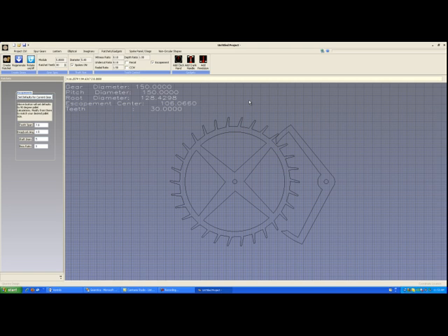The second part of the escapement is the pawl, this longish looking thing here with the 2 levers. This is actually not a longitudinal type device. It is considered as a round wheel, which interferes with this round wheel. They're actually meshing. They just look as if they're too close to mesh. The distance between the pawl and the deadbeat gear centers, this distance here, is extremely important. Even a deviation of 1 millimeter could hose your proper operating of the escapement in some circumstances, depending on the size of your clock.